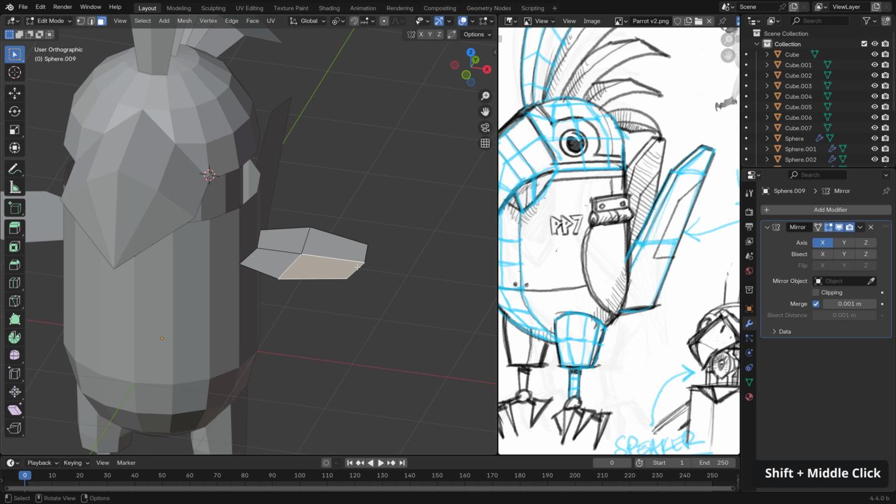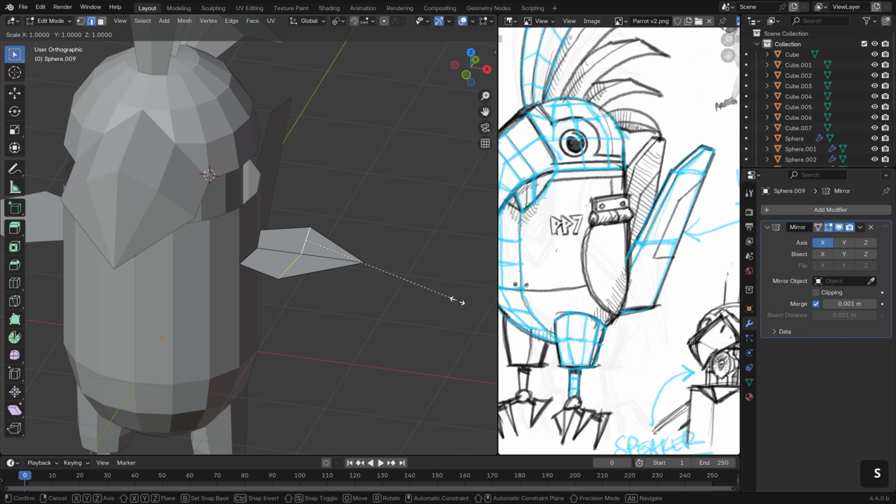So I think we want to go into a tip at the bottom here, so I'm going to select these two outside points and then the middle one and then merge at last. And we want a little bit more depth here, so I'm just going to scale 0 and then hit Control and B to create a little bit of a bevel here.